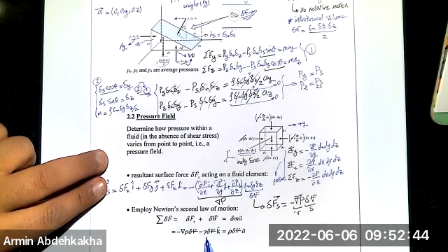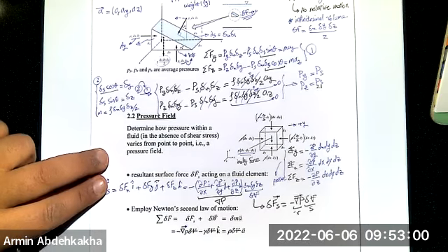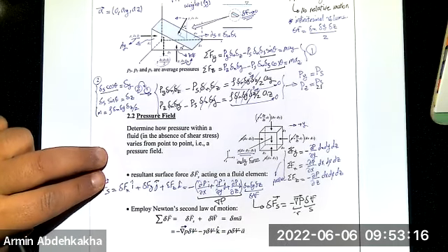The W is rho g times volume, gamma delta V in the K direction, right? If you have K here, it means that you have direction. Delta V is not a vector. But acceleration, the K direction, and the gradient of the P are directions.